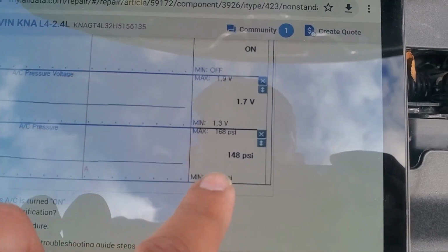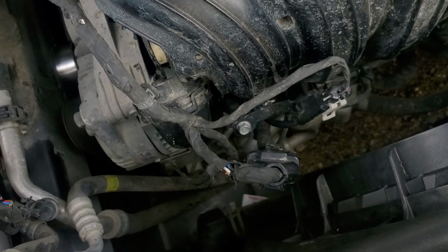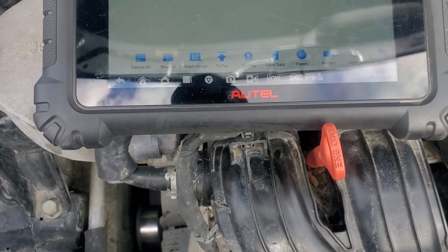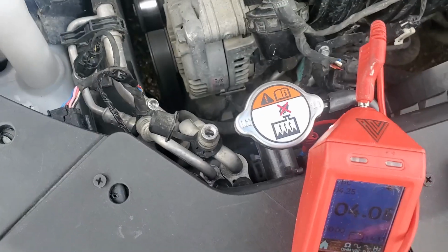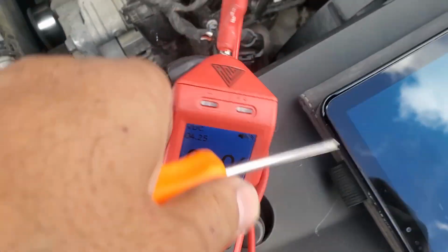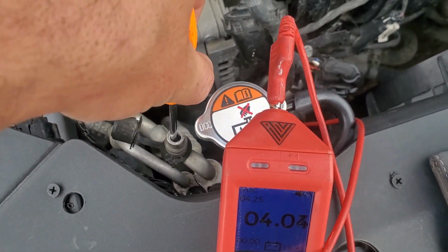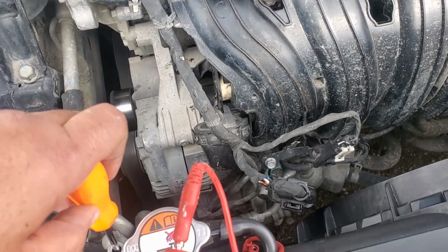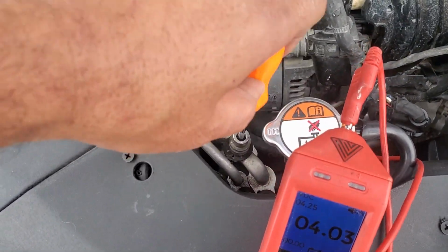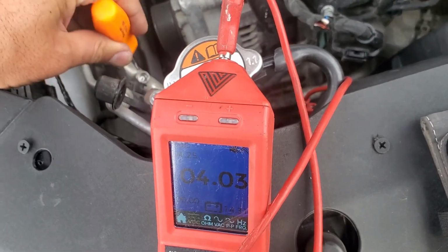But hold on. Was that a pressure in PSI? Yeah, PSI. I talked to him. They changed the radiator, so there shouldn't be anything here. He said he didn't charge it. Why this 510 though, PSI? Should it be 0? But right here, it's empty. The system's empty.